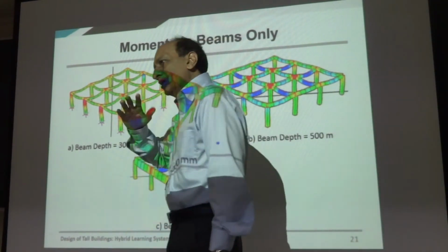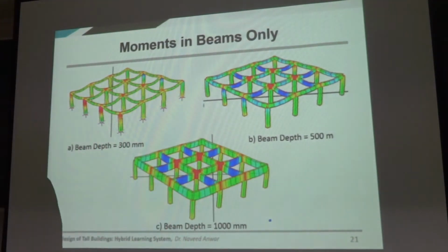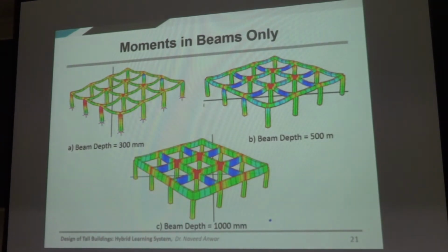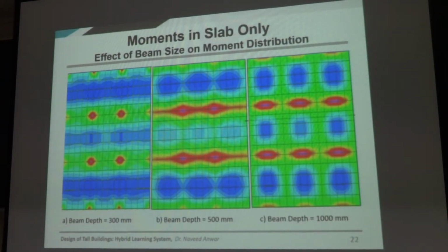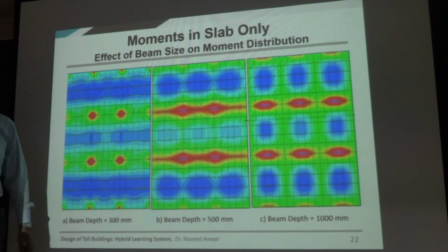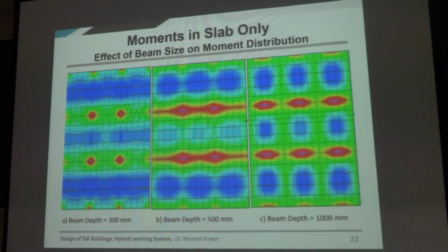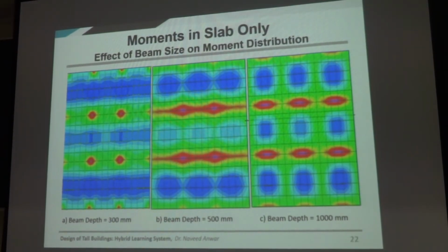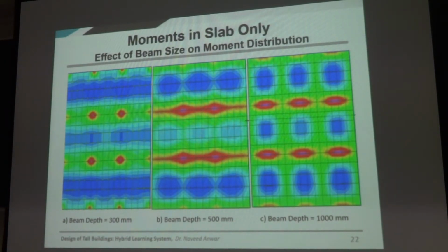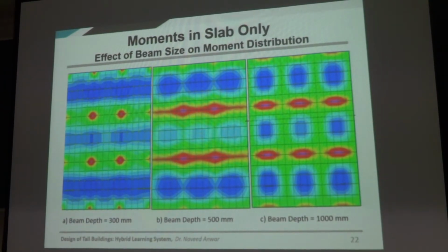So this gives you an idea how the relative stiffness of the systems change the distribution of load carried by the slab and the beams, and from the top you can also see it's like this. Now this leads us directly to the ACI method for design of slab systems. They have a single method for design of all kinds of slabs. They do not make any distinction between waffle slab, brick slab, joist, beam slab, and so on.